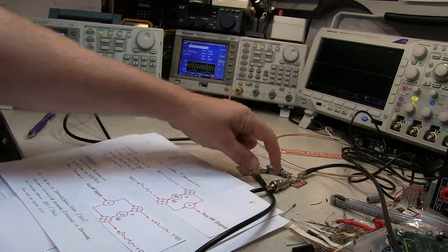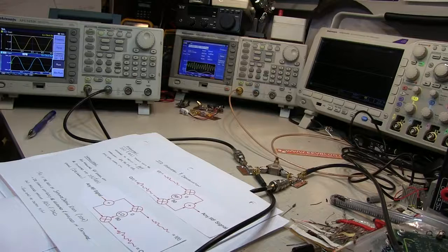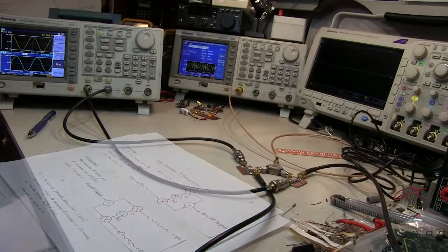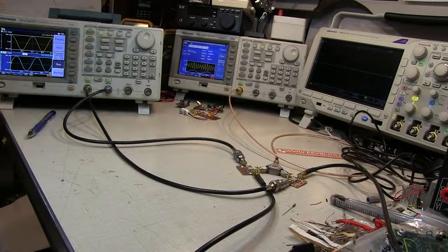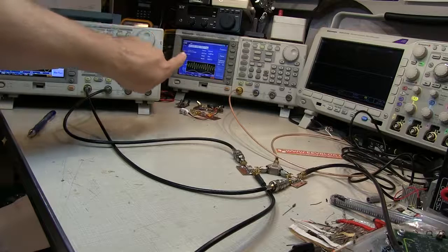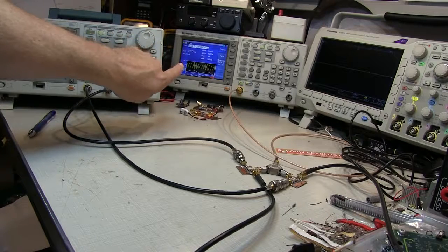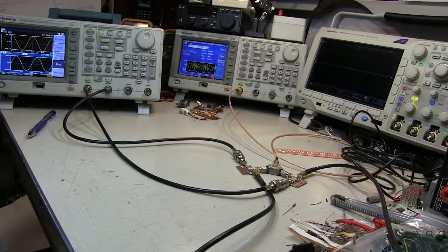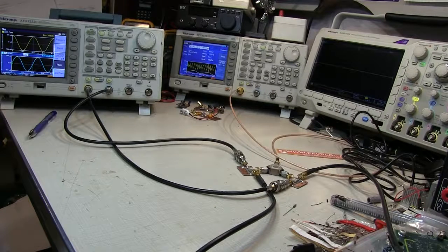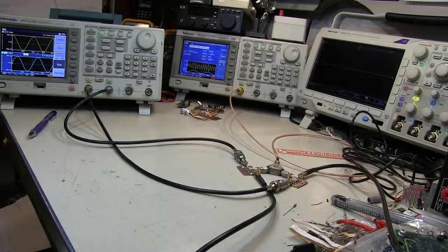So the output that we're going to be looking at on the scope is going to be just the baseband I and Q signals. These two signal generators have their references locked together, so that when I set up a carrier frequency for the modulated signal and the direct conversion quadrature oscillators for the mixers, they're going to be phase locked together, so everything will be perfectly stable. That'll make it very easy for us to examine the IQ signals in a nice stable way.